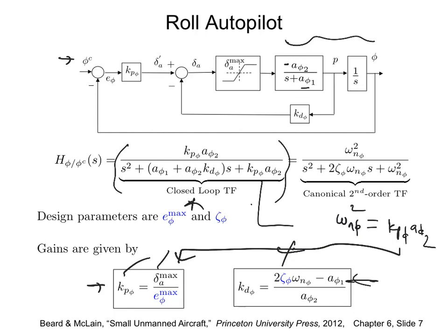So I would suggest, when you are tuning your gains, remember I told you that you can get a transfer function in MATLAB by giving the numerator coefficients and denominator coefficients, and then you can see its response by saying step sys. If you give a step command with phi equals 1, you will see if there are steady state errors and how fast it is converging. So you can then tune your gains.